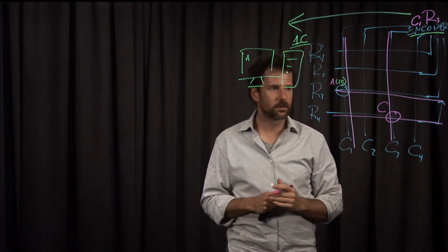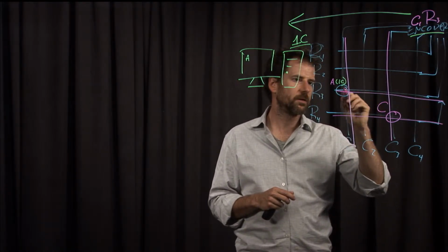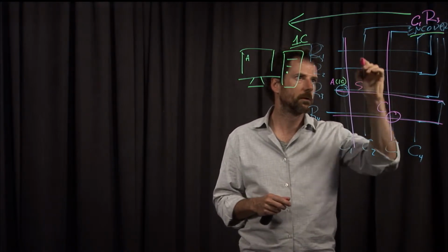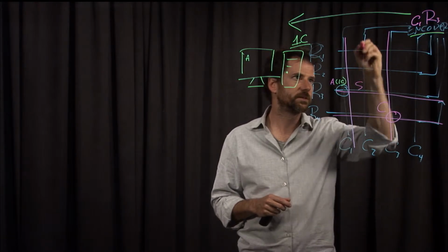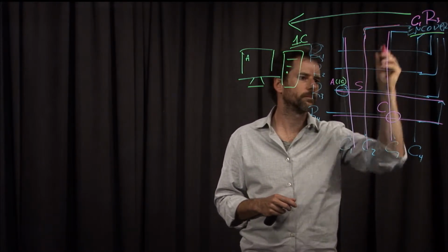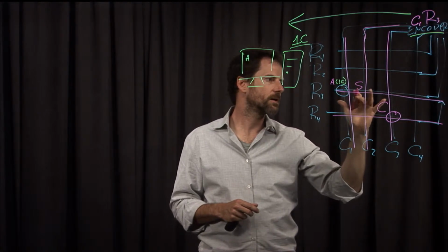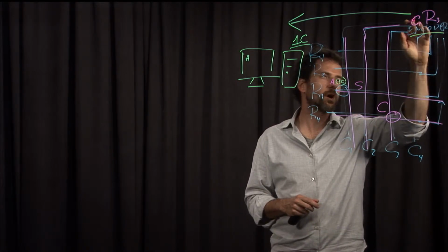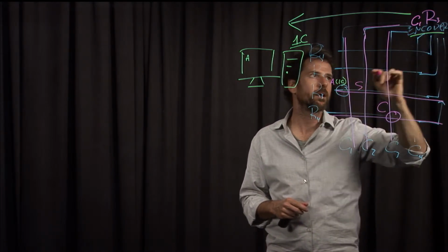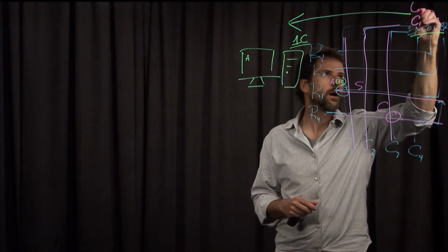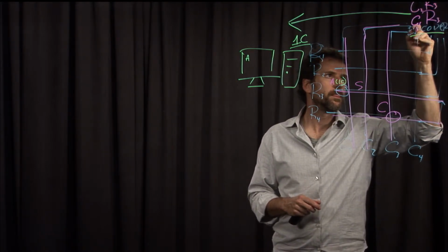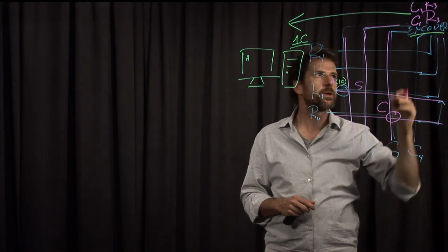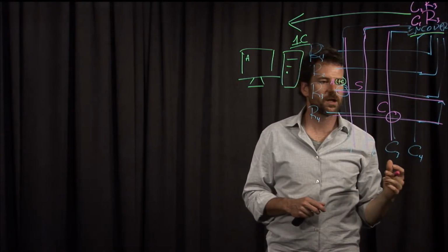More interestingly, what happens if while key A is pressed, you also press S, which might be in the same row, but a different column? Here, when I press on the S, the encoder is seeing what it saw before, column 1, row 3 for A, and now it's also seeing column 2, row 3. If both column 1, row 3 and column 2, row 3 are showing up, then we know that both the A and the S are pressed simultaneously.